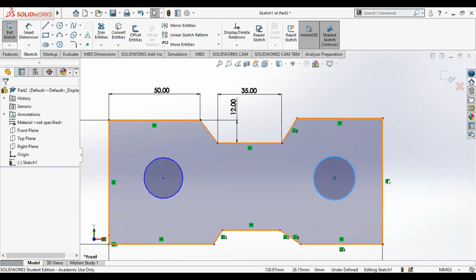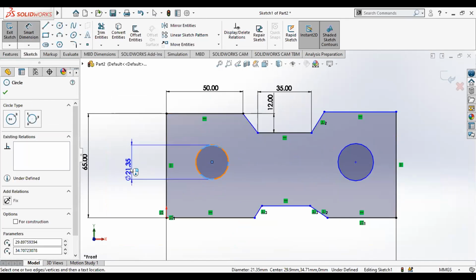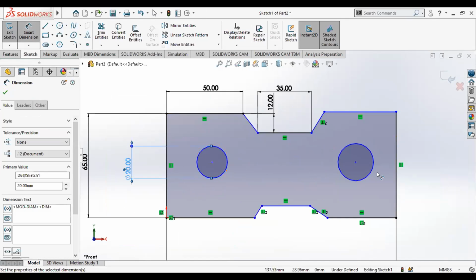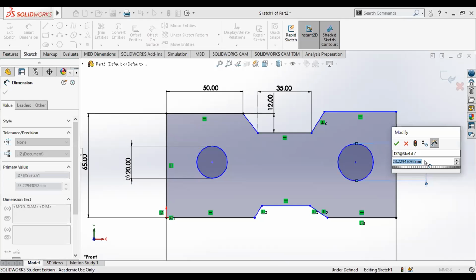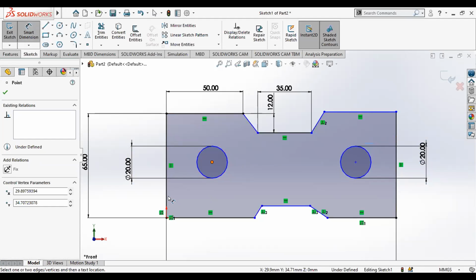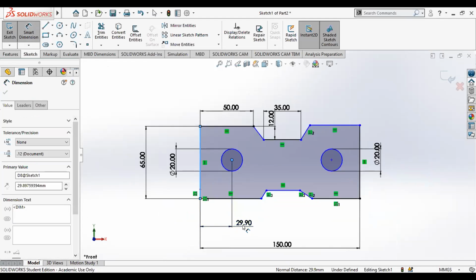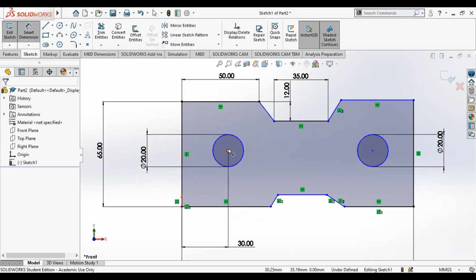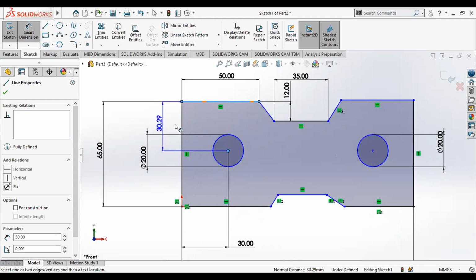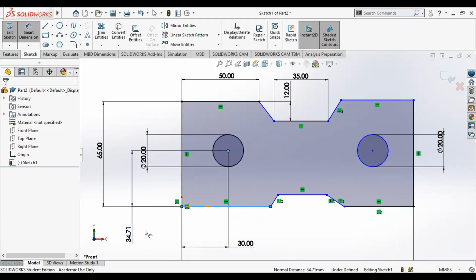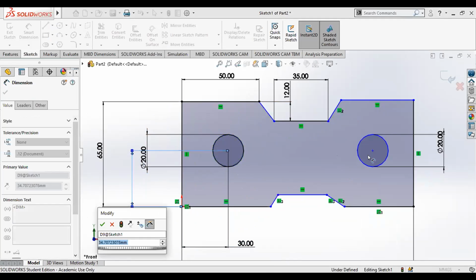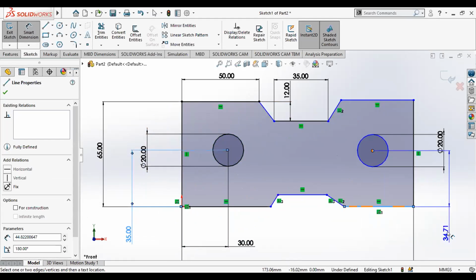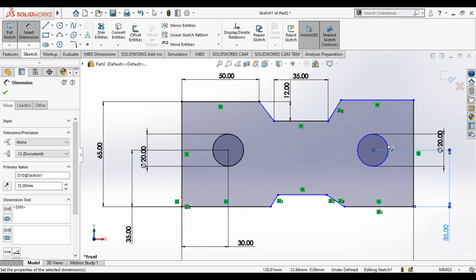Same also for your hole. For example, you have a cable inside the skin, or the rubber skin, or the tubes. You need to know the dimension, like the diameter. You need to know the diameter, and you need to know the position from the left. The position means the center point, measured from the top, or from the center point, measured from the bottom. These are all the dimensions you need to figure out. You need to do some measurements on the real product so that you are able to sketch.